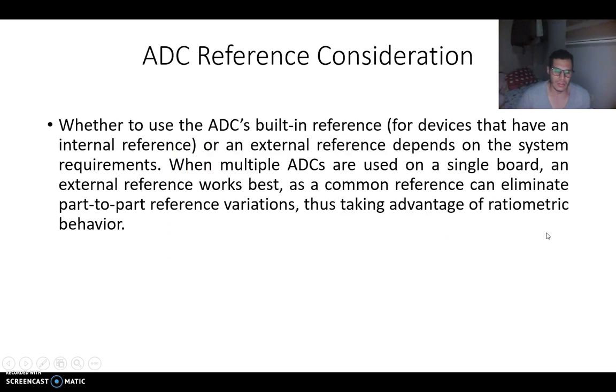ADC reference consideration: Whether to use the ADC's built-in reference for devices that have an internal reference, or an external reference, depends on the system requirements. When multiple ADCs are used on a single board, an external reference works best, as a common reference can eliminate part-to-part reference variations, thus taking advantage of ratiometric behavior.